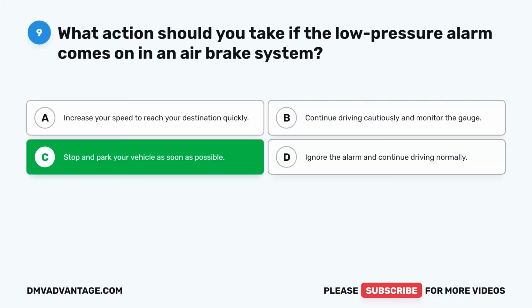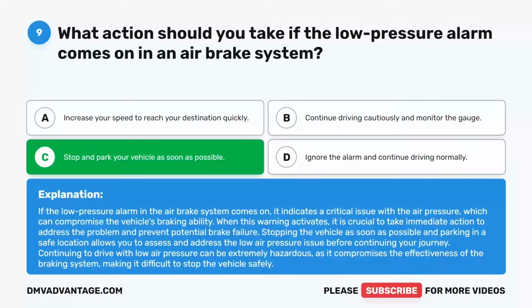Stop and park your vehicle as soon as possible. If the low-pressure alarm in the air brake system comes on, it indicates a critical issue with the air pressure, which can compromise the vehicle's braking ability. When this warning activates, it is crucial to take immediate action to address the problem and prevent potential brake failure.